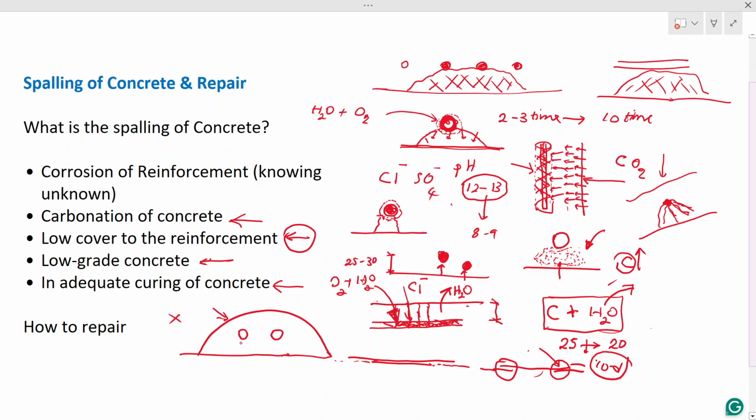Next thing is the concreting. What sort of concrete can you put in there? Usually in this kind of situation, with these slabs, you can't put usual, normal concrete. That's because when you pour the concrete and it hardens, its volume reduces. Concrete shrinks with hardening, so there will be a gap here. What happens if there is a gap? There is no attachment between the existing and the new concrete. Then a similar situation as happened previously would happen there also.